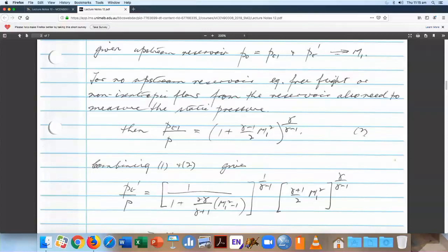So I get the Mach number from the total pressure and the static pressure. I put that Mach number into the relationship between the speed of sound, AT squared over A squared, and that gives me A, the speed of sound, and then if I multiply A by the Mach number, I get the velocity of the fighter aircraft, and I might need to know it.